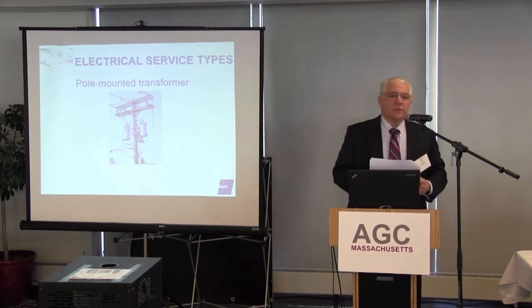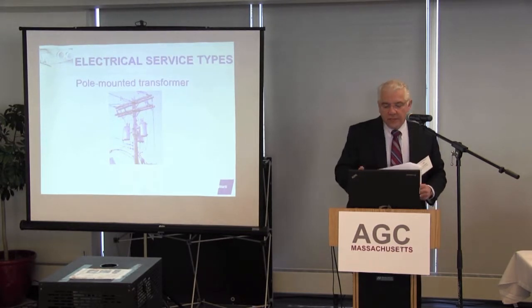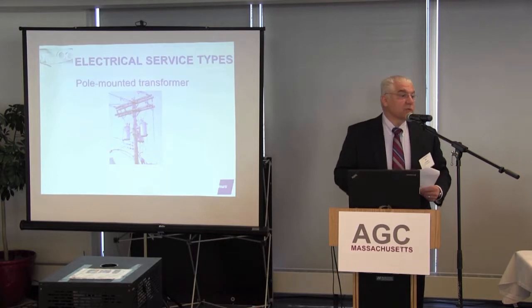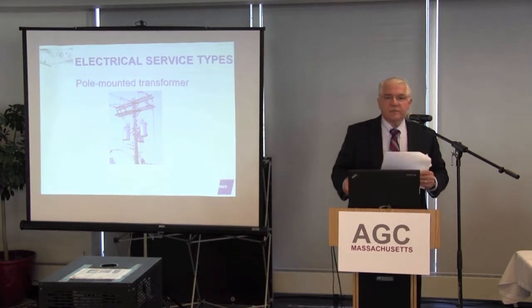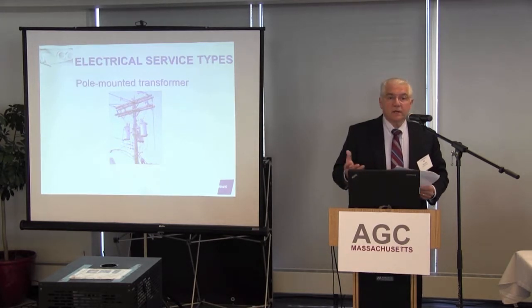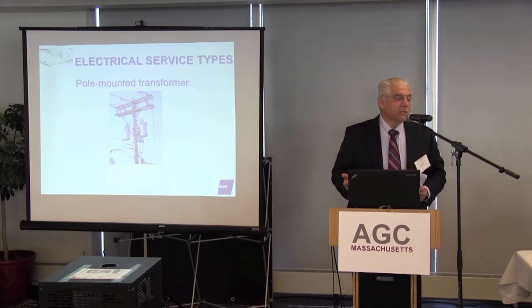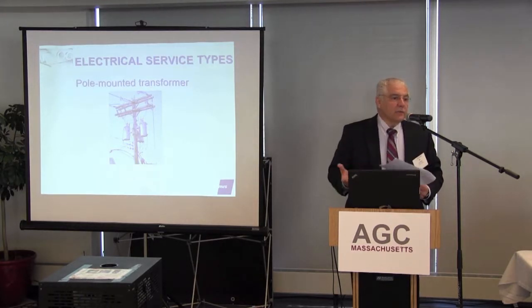So just think of the transformer as high voltage in and low voltage out, and that happens not only on the electrical service side, but also numerous times within the building when you're trying to transform voltage, as Will said, for a commercial building or a building with a large mechanical load. A lot of those feeds would be 480 volts.